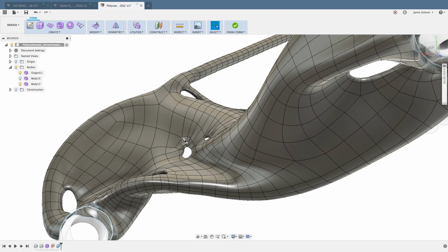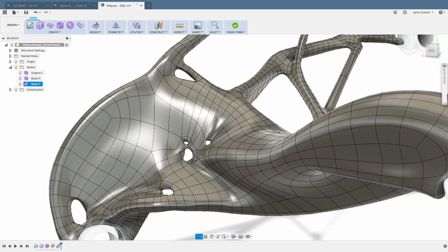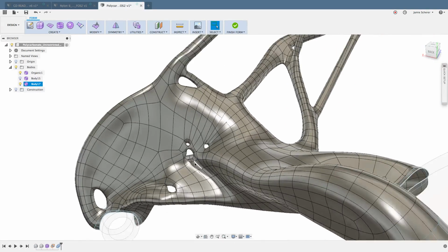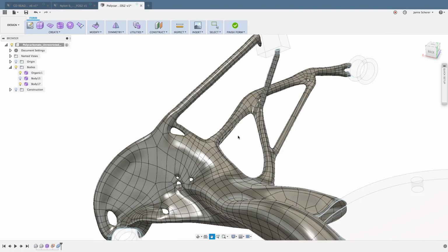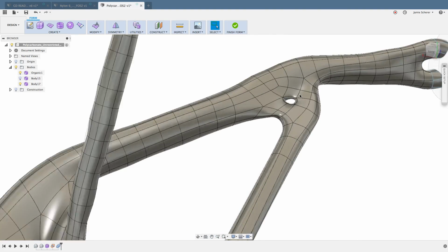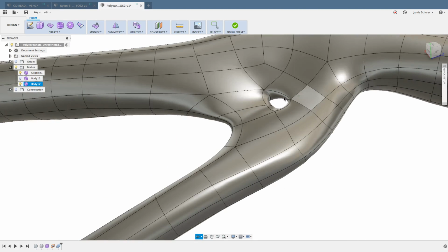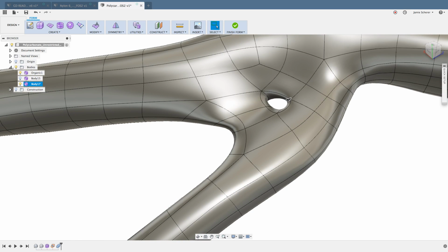And looking around, there are some really good examples here of geometry that I may or may not want to go forward with. I've got some holes in the center of my part here. The first one that we'll take a look at patching will be this little hole up here in the corner. Now, based on the loads and constraints that I put together, this is fine, right?